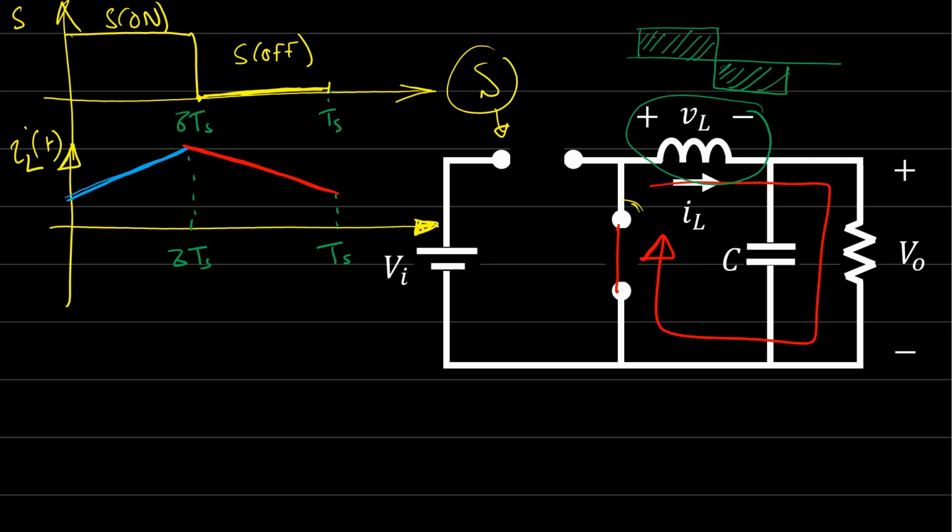When the inductor is discharged, then we have negative voltage. These two areas must be exactly the same value. Otherwise, the charge, the current, the energy will be accumulated inside the inductor, and gradually the inductor current will keep increasing until we reach unstable operation, or the device might be damaged.